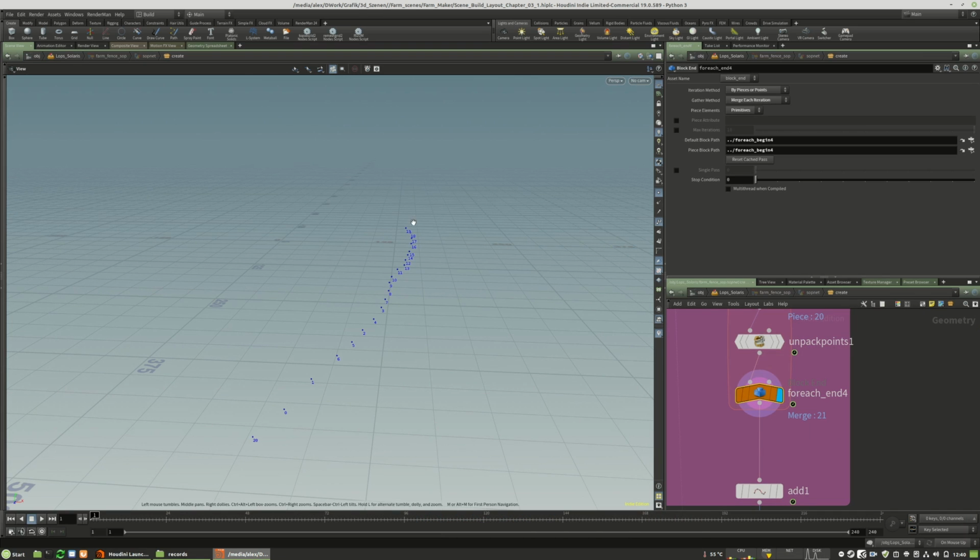So here I come back. I have played a lot with those values, and there's something that I want to show you. I have used the nudge tool in the layout and tried to move those points. By doing that moving, the point numbers have changed totally. So we have totally different numbering now, and this could make a lot of problems by trying to create the fence object.